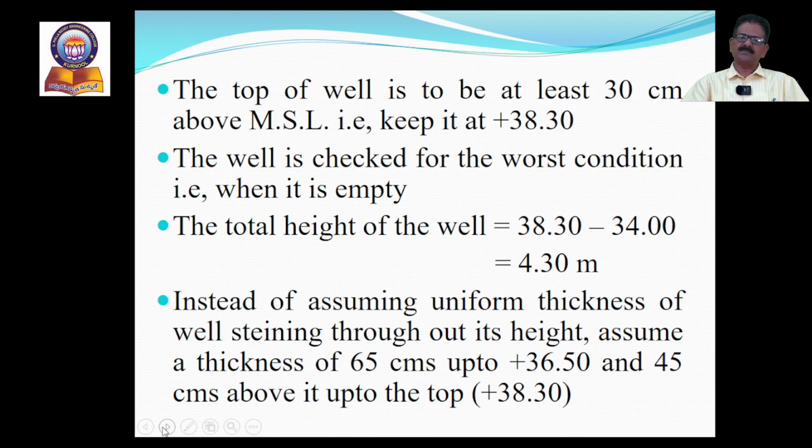In that case, there is no counterbalancing force acting inside the well. Why? Because on the outside of the well, a lateral earth pressure is acting. So we are going to check the stability and safety of the well steining. If there is any opposite force acting within the well, it is somewhat safe. But the critical condition is if there is no water or no earth in the well. Only the external force acting on the well steining is the outside radial earth pressure.